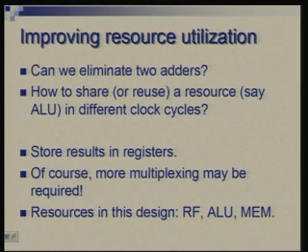You recall 2 designs of multiplier we discussed, 2 different types of design. One was array multiplier, where we had a cascade of adders with no storage in between, and the partial sum flows through all those adders. Okay. So, now as data flows through those, you can notice that each one is not getting fully utilized.